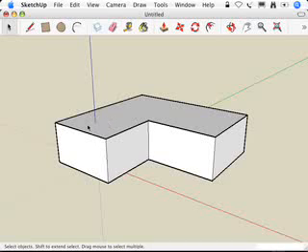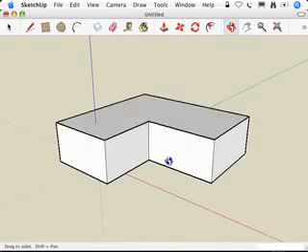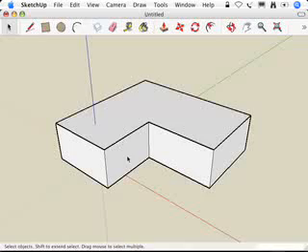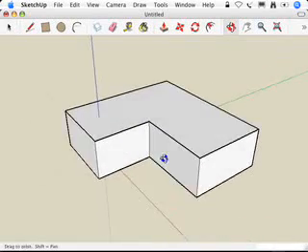And where that's really useful is if you've got an outline of a building that's actually quite complex. If you've got all kinds of loopy, swoopy curves and other lines and stuff, it's kind of a pain to use the line tool to retrace all of those, and that's where copying the edges inside the group and then pasting them in place outside the group can come in really handy for creating these kinds of faces that you need. Okay, that was a little bit of a diversion, but we're back into this now.